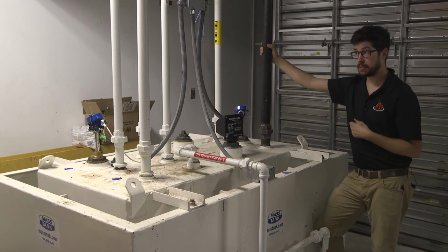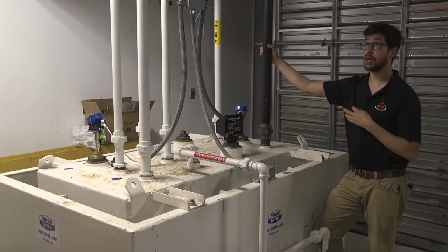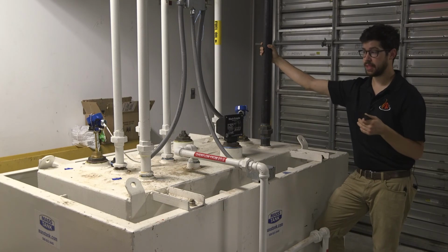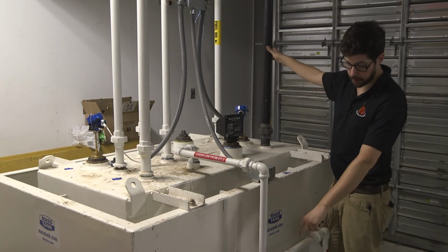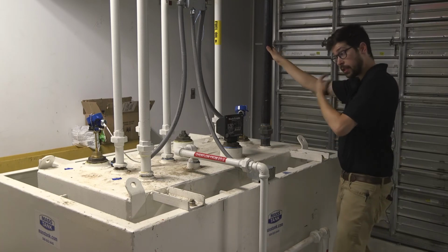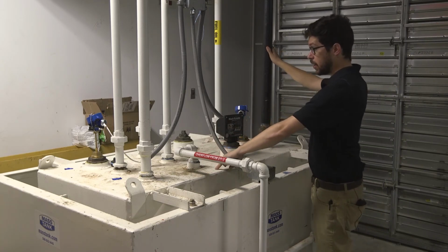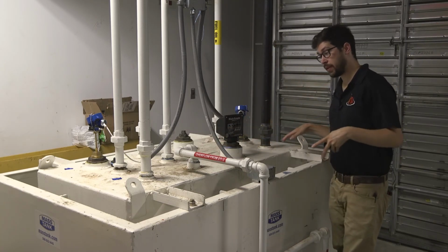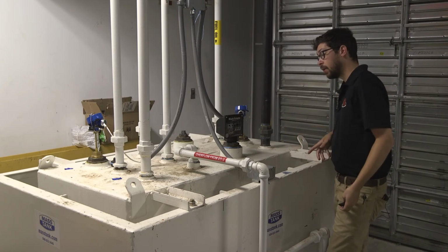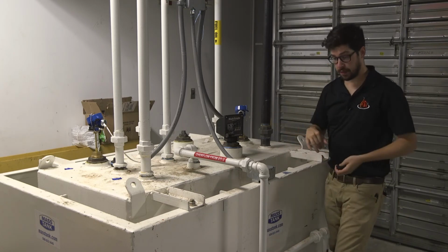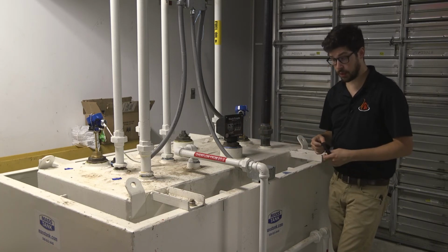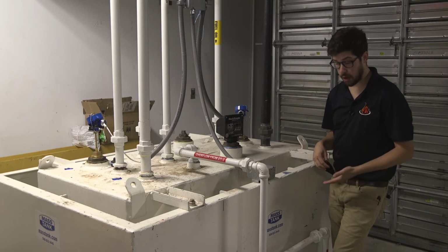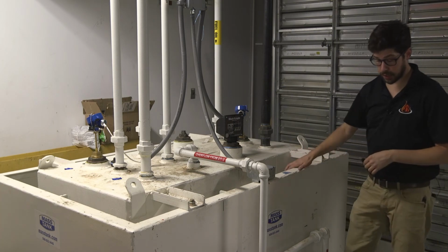When switching from system to system, of course, there are a couple 3-way valves in the system that would have to get swapped. One notably, which is right here, is the overflow. So this pipe here is in case all safeties fail, and the pump is still continuing, we want a place for that oil to go, which is going to go all the way back down to the storage tank.